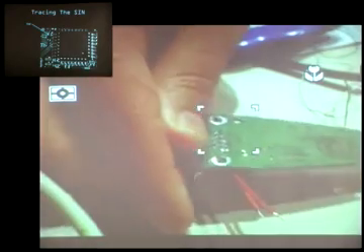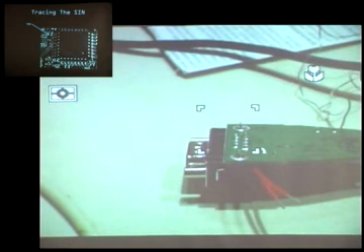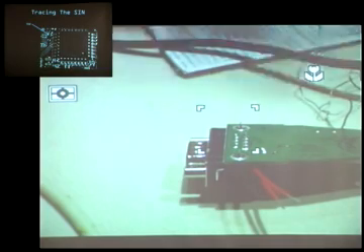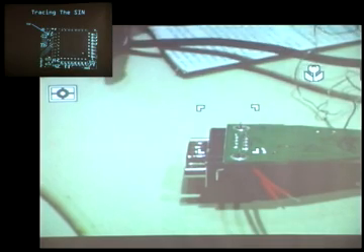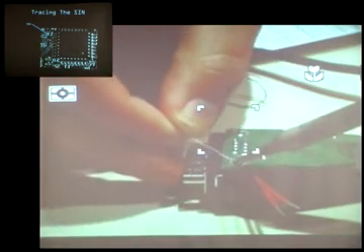Next thing you want to do is you want to hook a little ground wire into here. I could do a number of things. I can go ahead and get straight back to solder mask, do whatever. Actually, I'm just going to cheat. I'm going to hook onto one of the existing ground pins. So what I'm going to do is use these grounding tabs on the RS-232 connector. These guys right here are typically hooked to the board grounding. Actually, if you look close enough, you can see it.